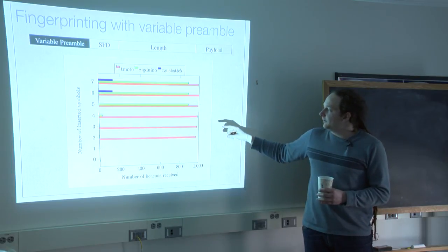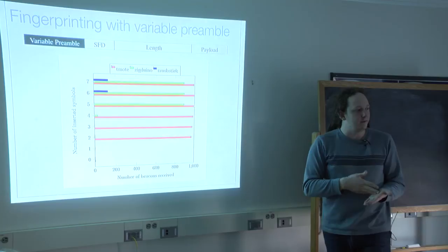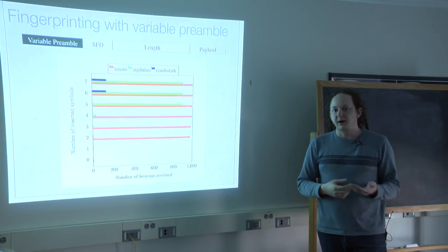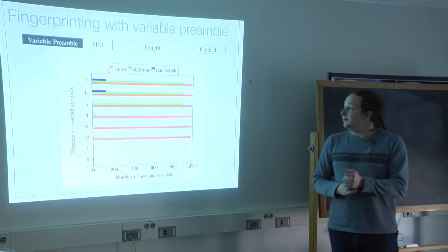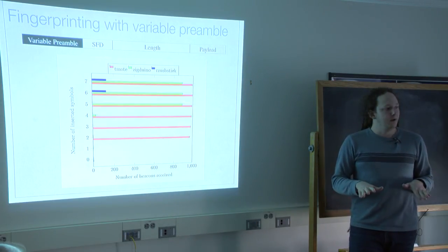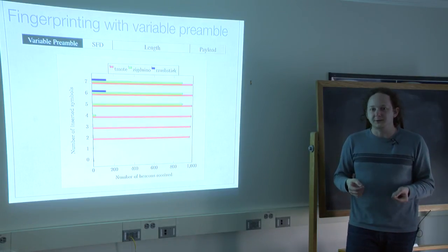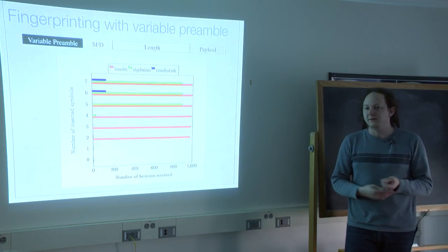The CC2420 matches the final 2 nibbles of the preamble as if it were a start of frame delimiter in order to reduce the number of false positive packets that it receives. If you leave any of these radios alone in a room with checksumming disabled, they will begin to give you packets even if there's no transmitter nearby, because they misidentify Wi-Fi traffic as being their own traffic.